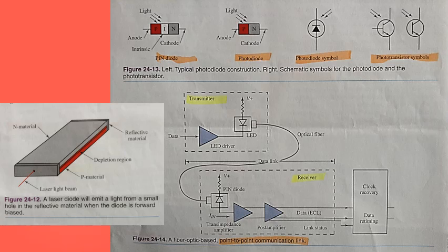The Avalanche diode reacts to light in much the same way as its name implies. The Avalanche diode is similar in construction to the laser diode. When light strikes the P-type material, both a hole and an electron are caused in the depletion region. The reverse bias voltage applied to the Avalanche diode is quite high in comparison to other forms of detector diodes.